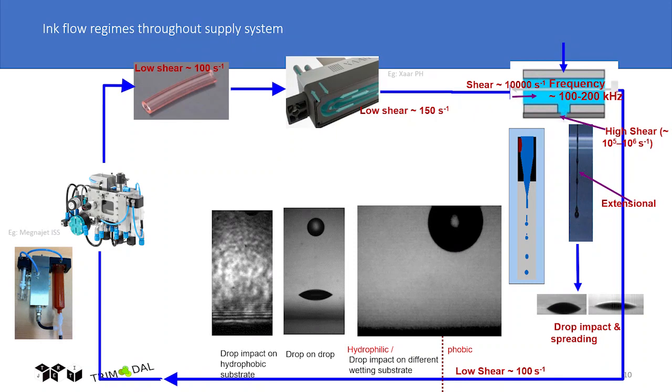The strain is very, very low. So that's why you apply the acoustic pressures and all that, you take care of it. And how much it dampens it. It's a dynamic, it's a time scale. So you really need to look at the dynamic. The problem is there aren't any rheometers that can do the dynamic in this time scale. Most commercial rheometers you buy would be 100 hertz at the maximum. And again the extension, how would you do it?